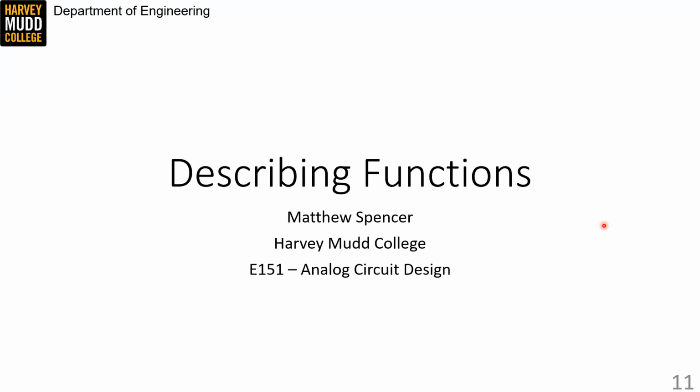In this video we're going to look at a mathematical technique for analyzing nonlinearities in our oscillators, which is called a describing function. This is just a glimpse of the world of nonlinear control theory, which is full of really fun math and modeling. However, I'm picking this particular technique because it can give you some insight about the amplitude of oscillation and about whether an oscillation is sustained.